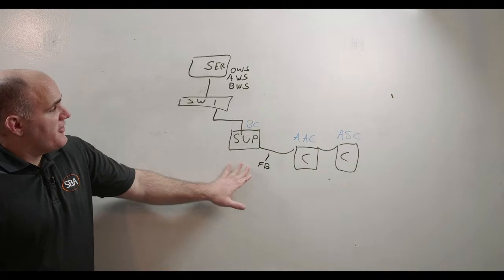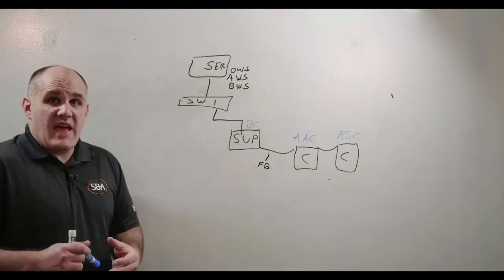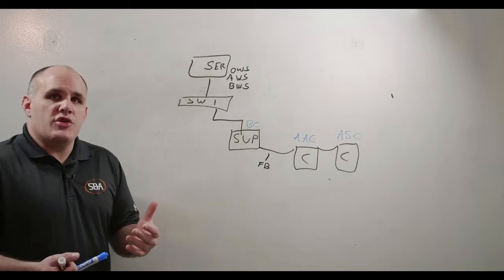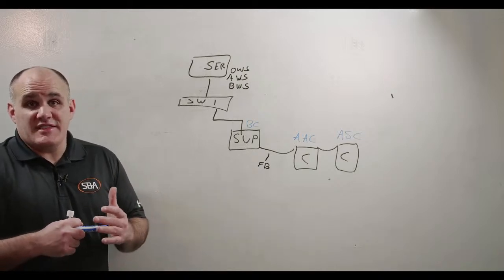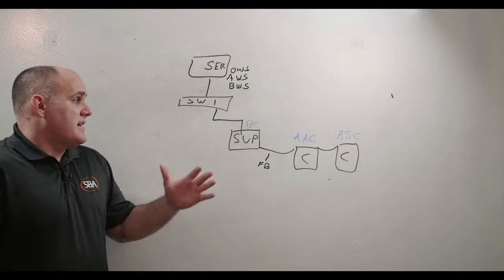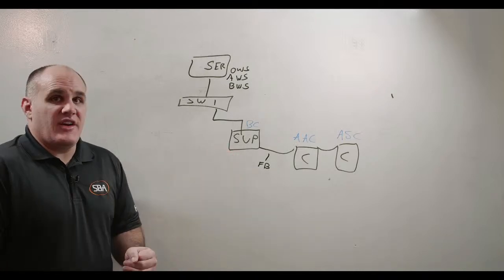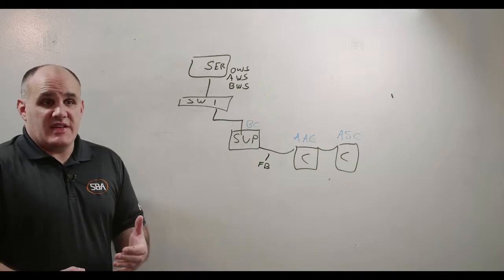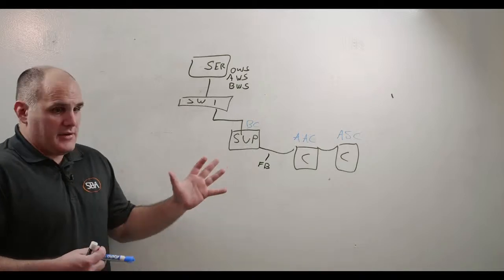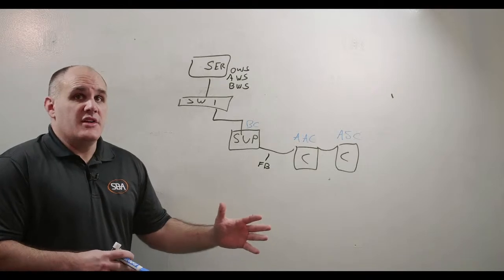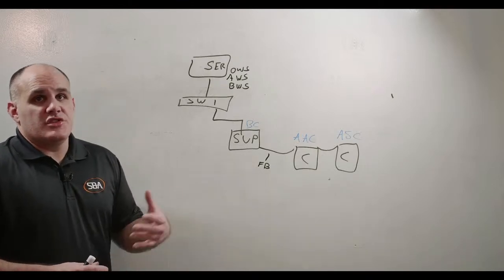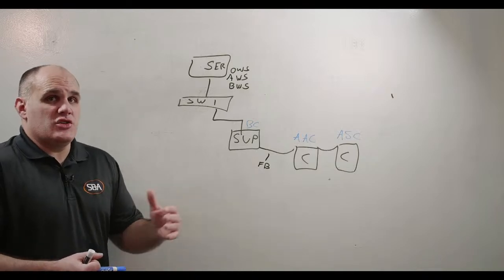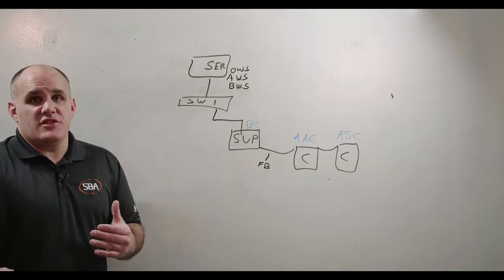So supervisory devices can have visualization. Now the problem begins where you have multiple supervisory devices in a site. In order to see the multiple different visualization suites, like, okay, floor 1 is covered by supervisory device 1, floor 2 is covered by supervisory device 2, you have to go in between the different supervisory devices.